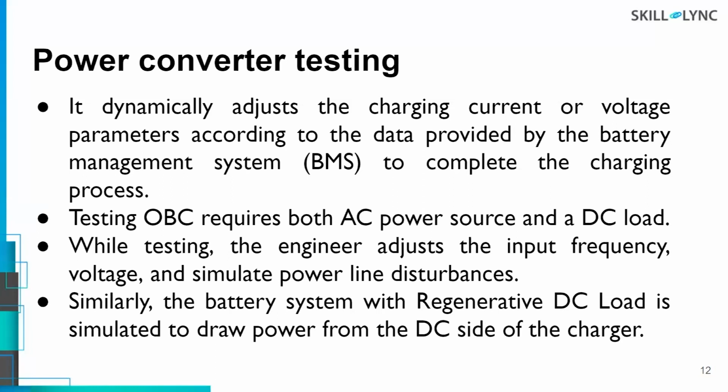It is going to check your state of charge, state of health, the protection part, and the charging part. You may have heard about cell balancing. Even if you're taking each and every cell in your battery pack, even if you select the same chemistry, it will not be exactly the same. It will have some changes, which puts the system in an unbalanced state. At that time the BMS is going to manage this properly.